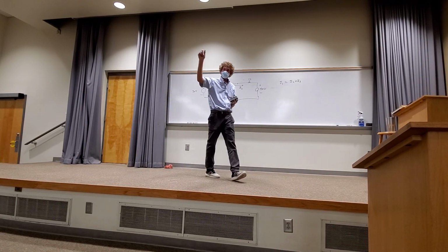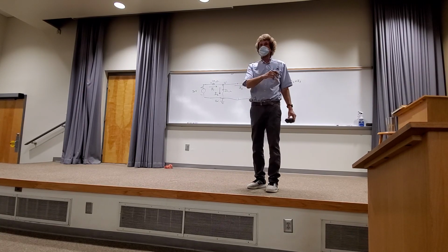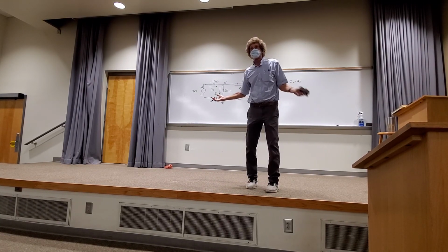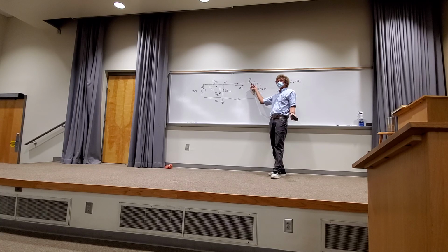Yes? How do you know the direction of I3? I arbitrarily put it that way. I can make it any direction I want, but then what? I3 here would be the voltage on this side, plus V, minus the voltage on this side, 40, divided by R, right? It could be negative, doesn't matter. It comes out in the wash. You okay with that? Let's just do this.